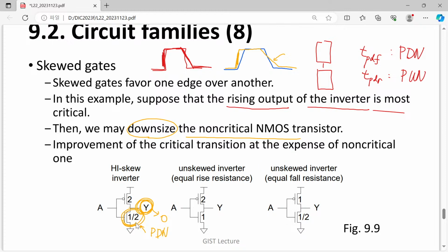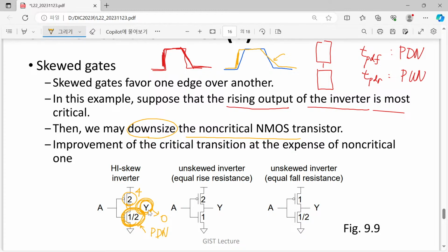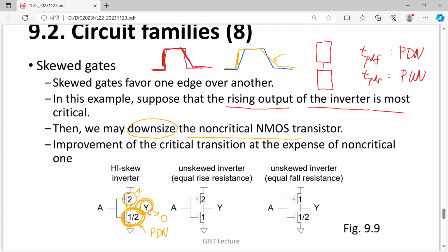then you know that now we have a much weaker transistor, and the relative strength or relative width of our PMOSFET is 4 times wider. So since it is 4 times wider, it will take quite a long time for our NMOSFET to pull down this relatively huge, greater capacitance seen from this Y node.